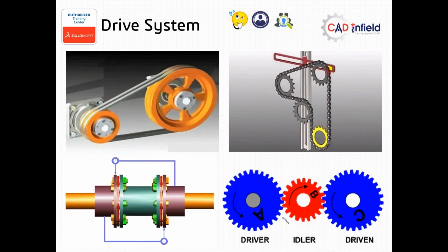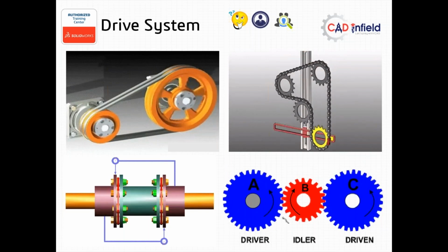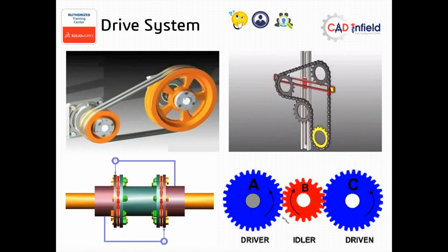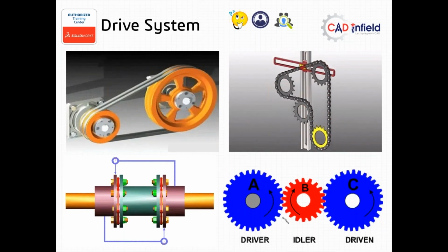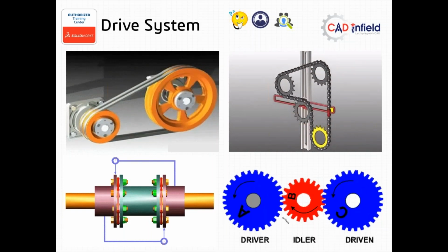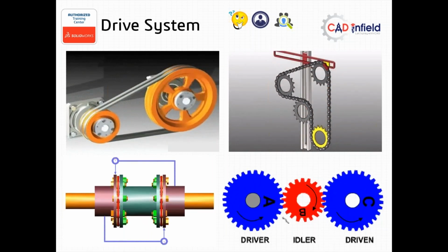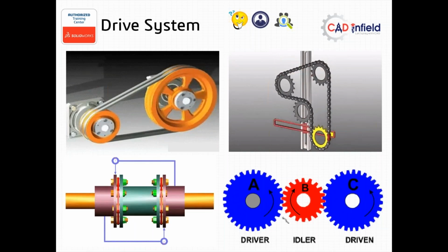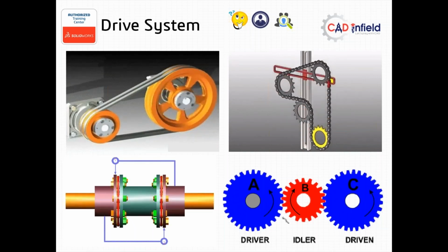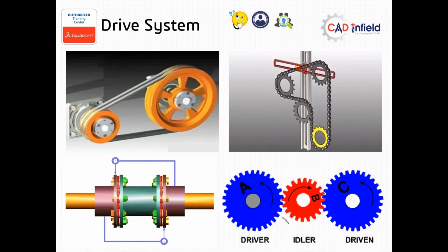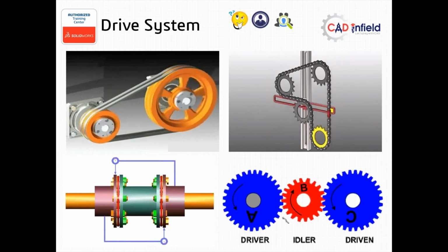In coupling, we have a flange. There are lots of couplings. Here I have taken the coupling which has a coaxial axis. If there is a certain misalignment, we have an Oldham coupling or a universal coupling. These applications are different, but you understand the axis of the shaft for this particular example is collinear.